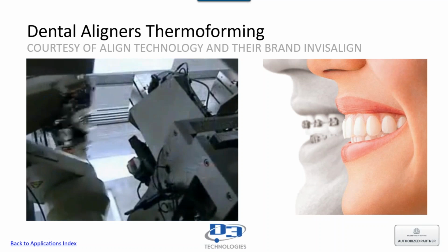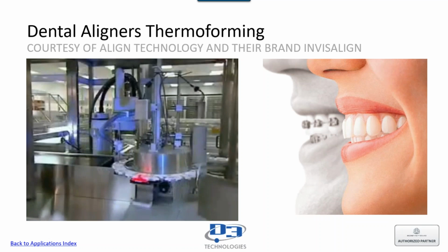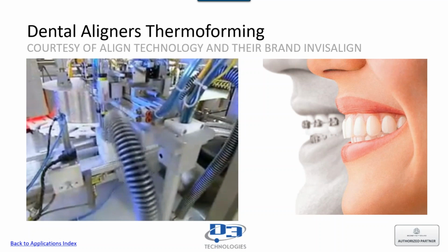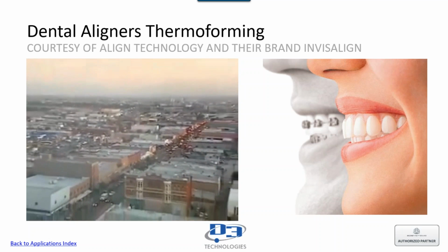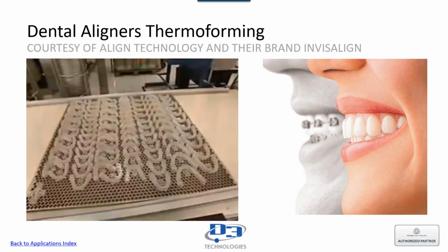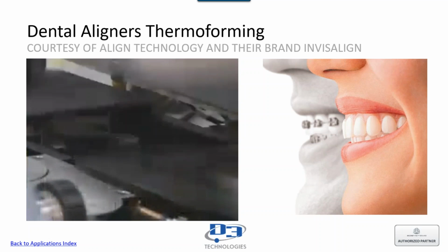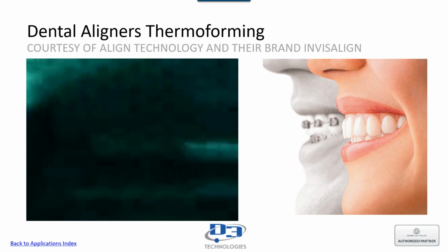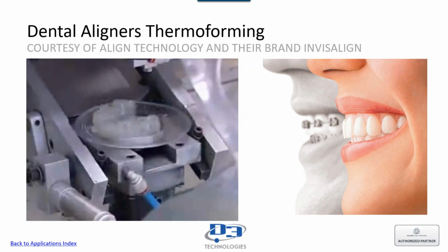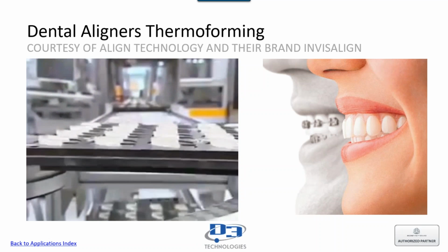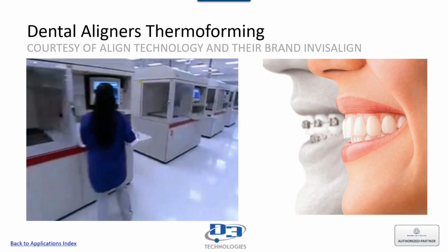create its reference models. So now a dental impression can be taken by your local dentist, and then it's scanned, and then the sequential steps are taken to straighten the teeth as defined, typically between 30 and 40 of them. Each stage of the treatment is 3D printed in a full factory floor of our SLA printers, and then they are loaded into an automated aligner forming system that heats, forms, and laser marks the sheet plastic over each plastic model. So just some good information about how mass production is actually being worked with our 3D printers today.